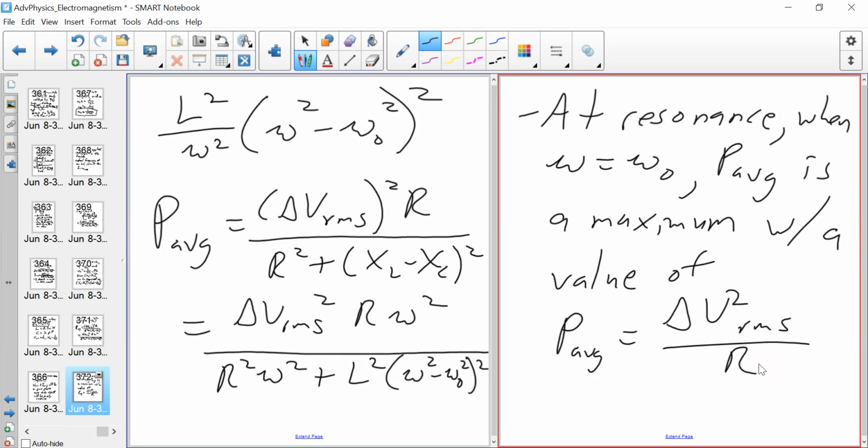Like I was saying before, when you make an RLC circuit have its current and its voltage in phase, you basically get DC circuit conditions. We tune in to that particular frequency that makes this circuit operate this way.